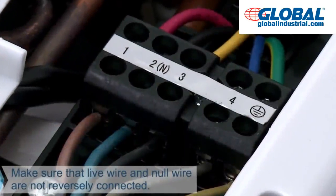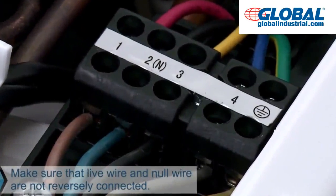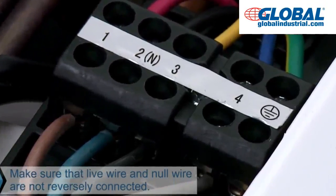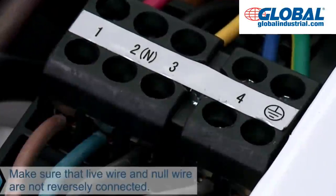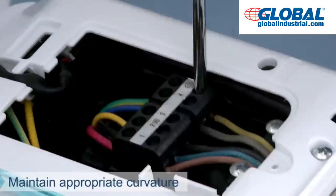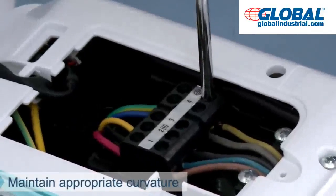Special attention should be paid if live wire and null wire are incorrectly connected. The air conditioners may not work regularly as a result of malfunction. Maintain appropriate curvature to avoid the loosening of wire terminal under stress.